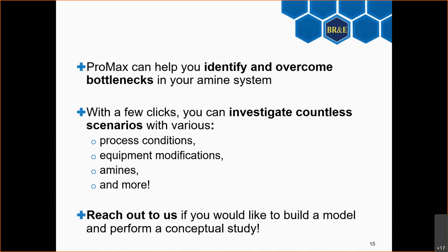Well, why not? I'm going to share the simulation with you. You can definitely try DEA with piperazine. It would be interesting to see how it compares. Or you can play with how much piperazine you're using. There's a lot of things you can easily put in ProMax and see how it compares.